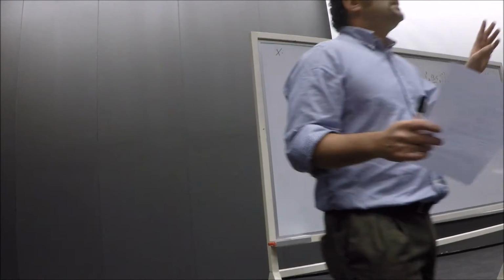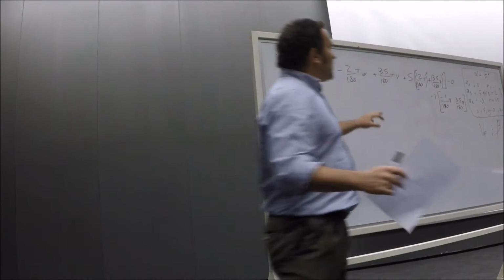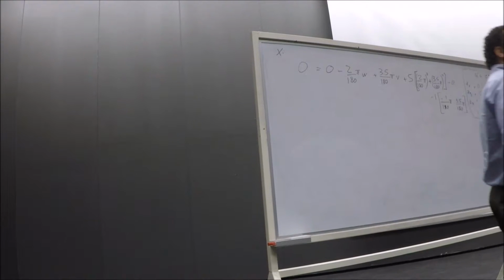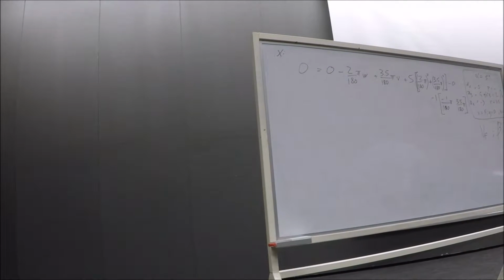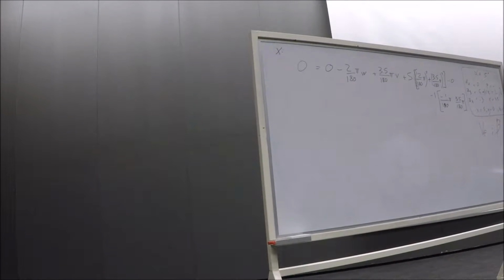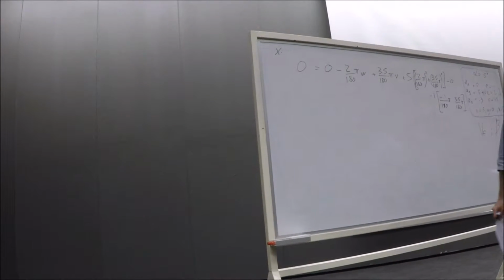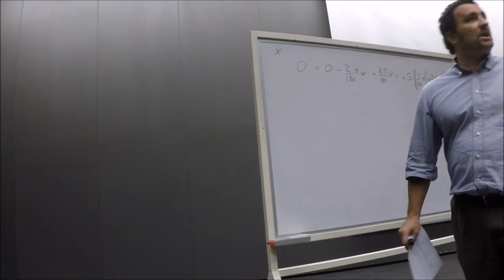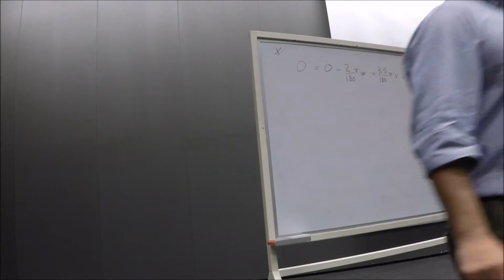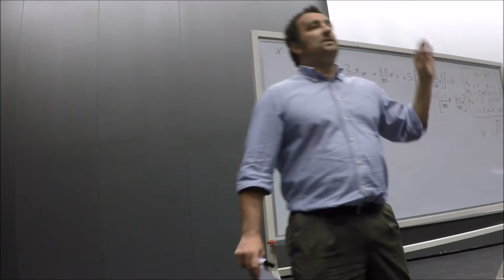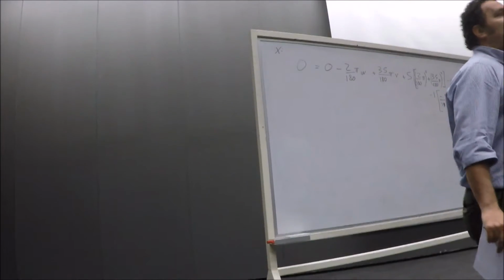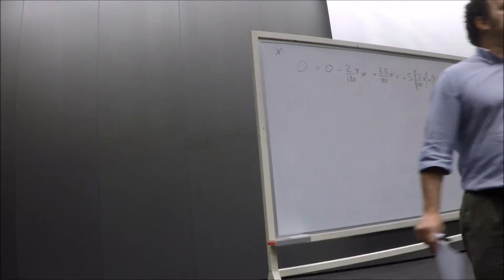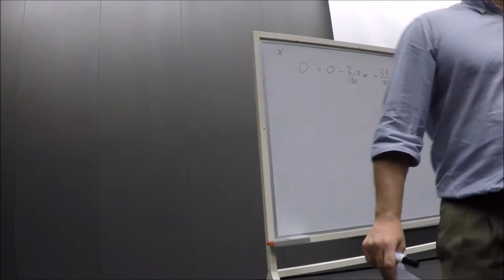If your velocities u, v, w are constant, then u dot, v dot, w dot are 0. The question mentioned that the aircraft is in steady state. It means it isn't accelerating. In general, you can always consider u dot, v dot, w dot, and omega dot, so the angular acceleration, as being 0, unless clearly specified in the question. Okay?